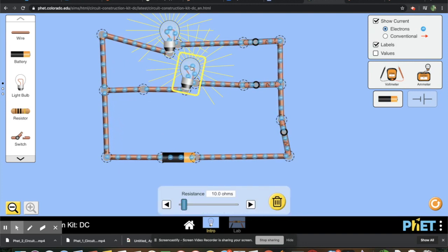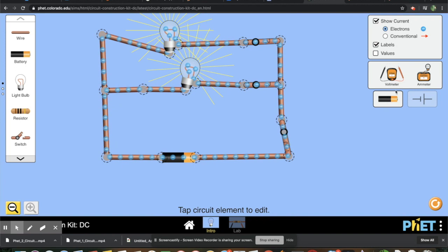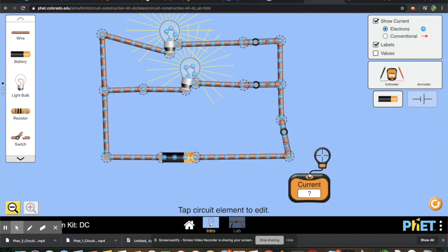However, bulb 3 is clearly affected. And let's just check some other things. Did that affect the overall current? Yes. Notice it's 1.8, before it was 1.35. So the total current went up a bit, which makes sense because we eliminated a resistor.